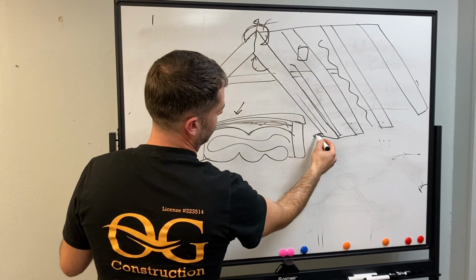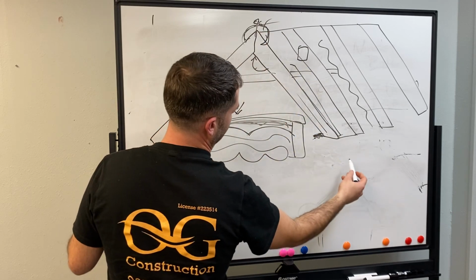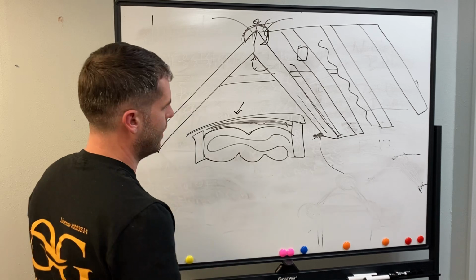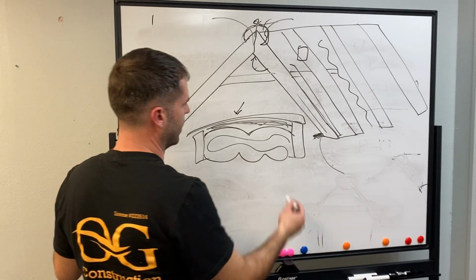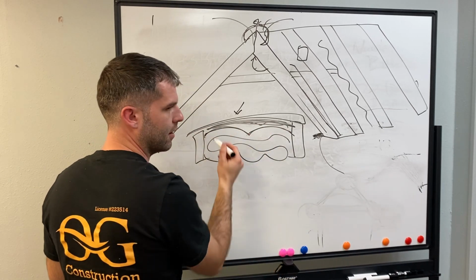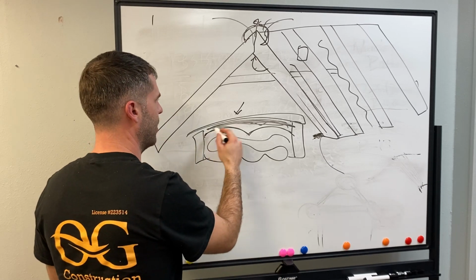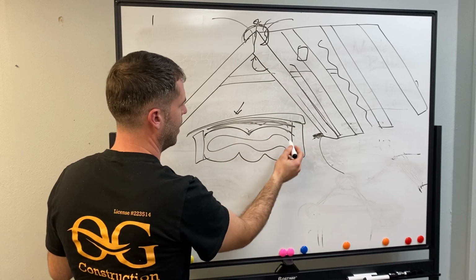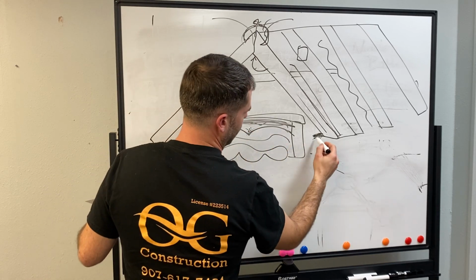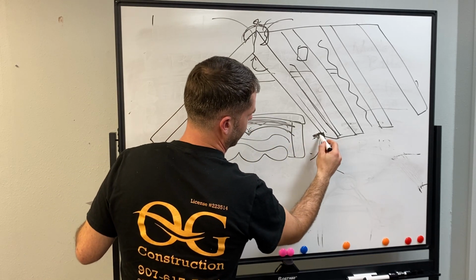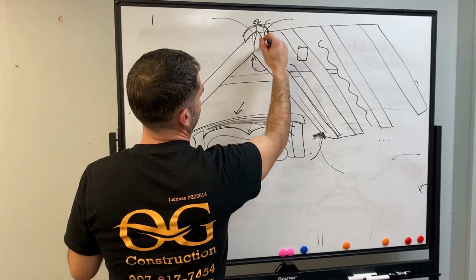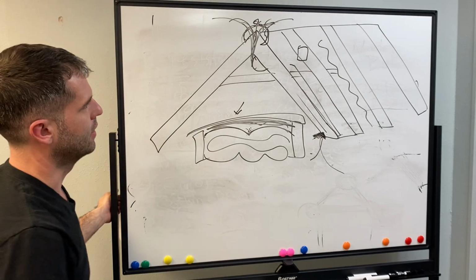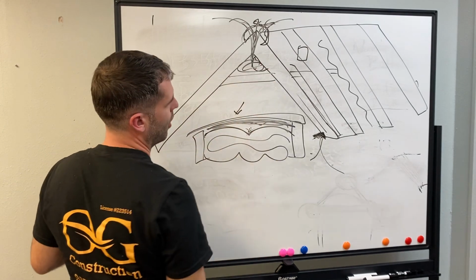The reason you have soffit to ridge is the pressure. This goes in and it goes out. Okay, if you don't do the insulation correctly and you don't use something like this, they sell them, some are plastic, some are foam, there's different types that you can use right here. If you don't do this and you still have a soffit vent where it doesn't do anything, the air gets stuck and the only thing you have is air coming in and out right here, which is very limited at that point, causing this to be damp and causing problems down the road.